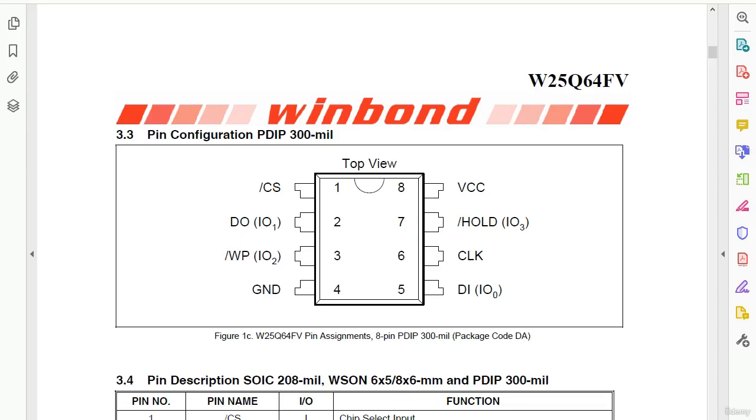Hi again. In this lecture, we're going to see the BIOS chip pin configuration. We're going also to see how to download the circuit diagram of every BIOS chip you want. We're going also to see the schematic of the BIOS chip, and of course we will see some real BIOS chip in the motherboard, and we will use the multimeter to check its pins, to check the VCC pin, and of course to check the ground pin, etc.